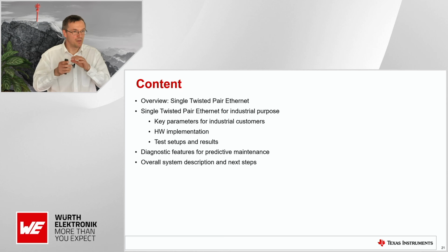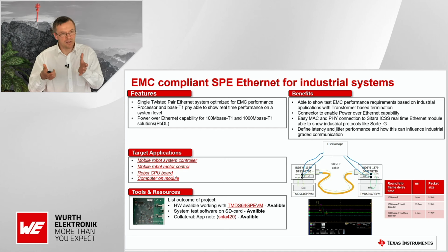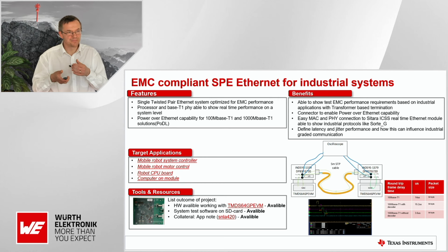There are also some other very cool features within the PHYs that make them very interesting for industrial systems. Now, looking again here, you see the system here with the EMC, EMI measurement. One thing that I wanted to quickly mention on it is the PHY also has some capabilities to do diagnostics inside the PHY that you can read out on the serial management interface.